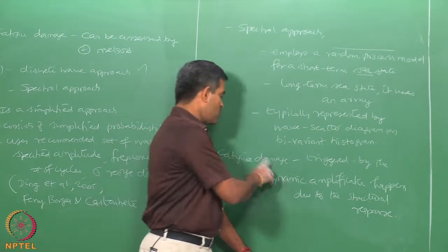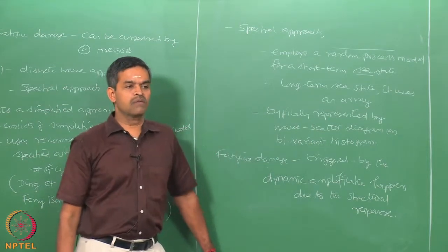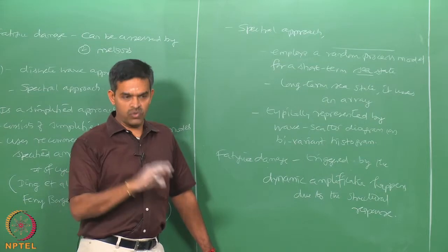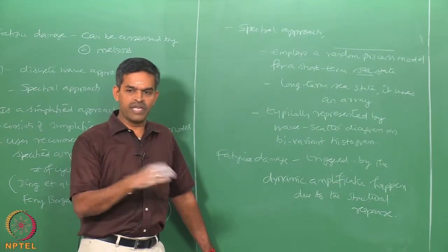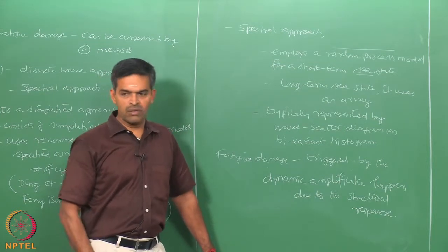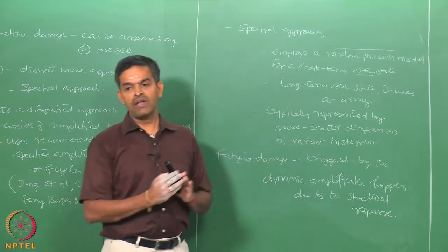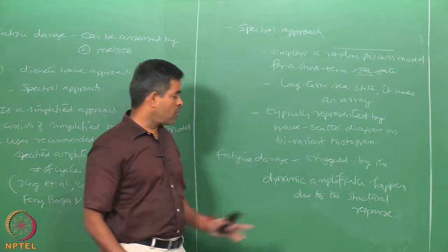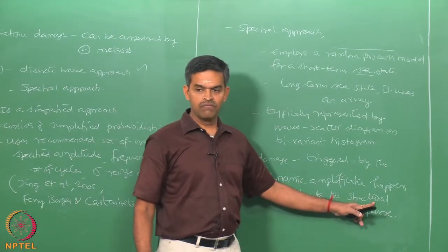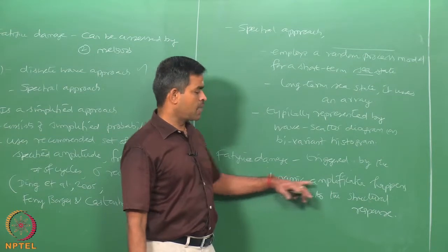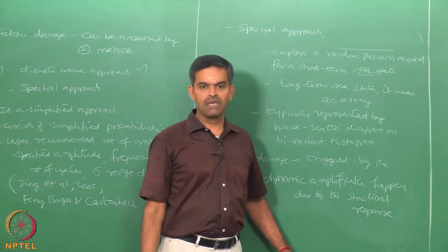So, the damage caused by the stress concentration factors at the tubular joints because of reversal of forces or reversal of amplitudes or directions of wave load acting on these members will cascade the effect of failure in the presence of larger responses, which amplifies the failure because of the dynamic amplification factor presence in the given system.